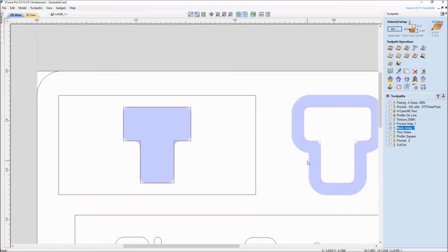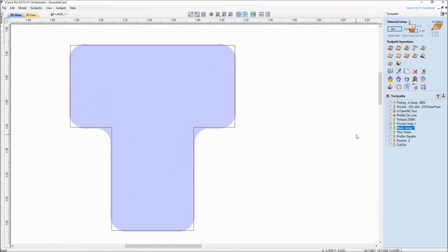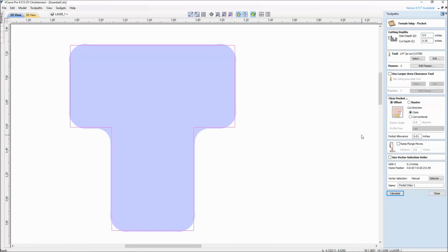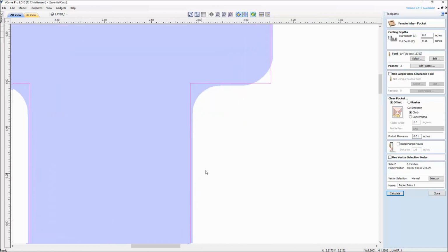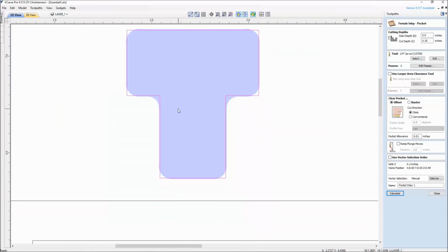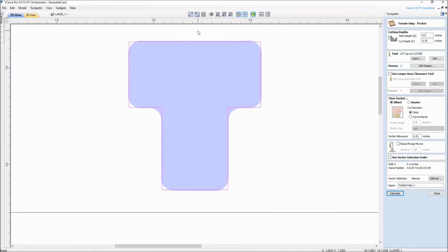This is an example for people to put their hands on and pull the part in and out. So this pocket right here that you see, the female portion, pocket inlay, actually has a tolerance to it, which is called a pocket allowance of 0.01. And that 0.01 is actually 0.01 on each side. So this overall has a tolerance of 0.02.